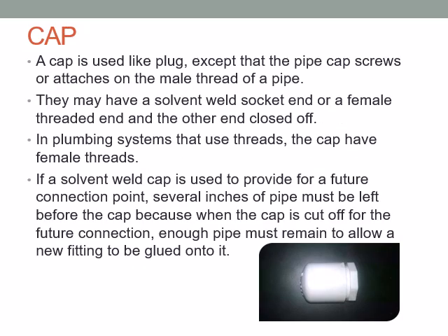Next is about the cap. A cap is used like a plug, except the pipe cap screws or attaches on the male thread of the pipe. A male pipe is nothing but one which has the thread outside the pipe. They may have a solvent weld socket end or female threaded ends and the other end closed off. In plumbing systems that use threads, the caps have female threads.